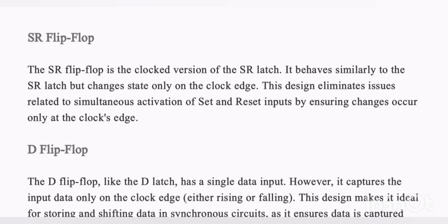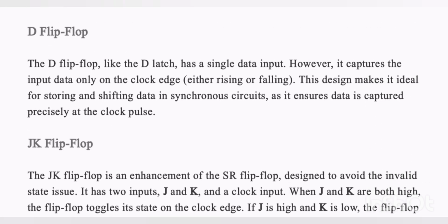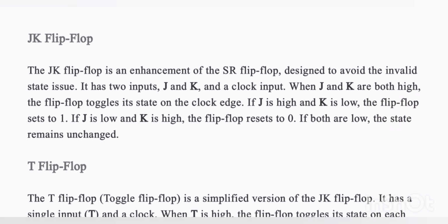D flip-flop. The D flip-flop, like the D latch, has a single data input. However, it captures the input data only on the clock edge, either rising or falling. This design makes it ideal for storing and shifting data in synchronous circuits, as it ensures data is captured precisely at the clock pulse.